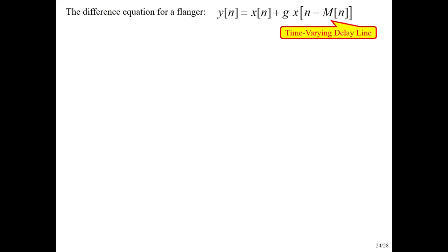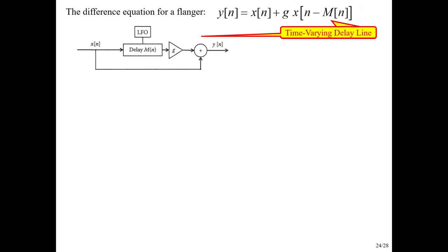Let's look at it mathematically. So what we need is one signal added with some weight to a delayed version, and this delay is going to be time varying. So we know how to get this. We run the signal through a delay line, we sweep back and forth our output point, and we interpolate the cells to get that value.